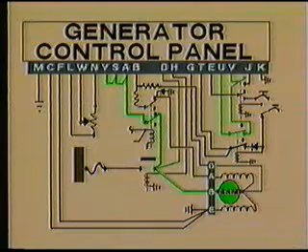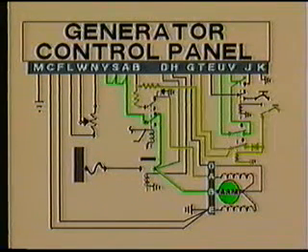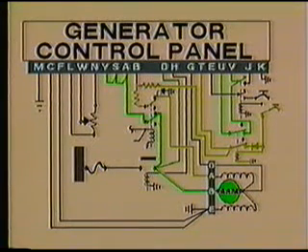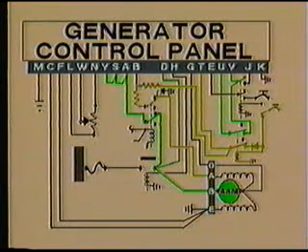the generator's output. The second set of contacts in the reset relay provide aircraft bus voltage to hold the panel's reset coil engaged and to provide a small trickle voltage via a 400 ohm resistor into the field circuit, thereby providing a secondary flashing of the field.